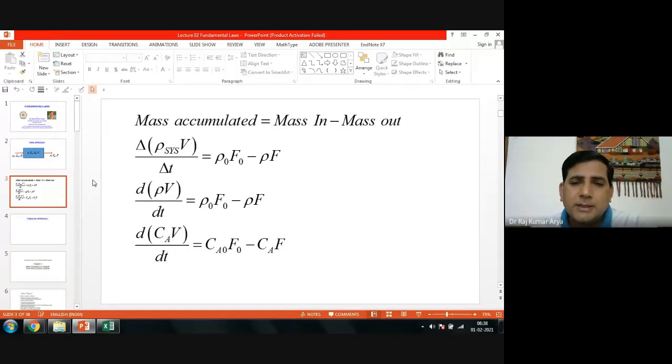So you might be wondering about the case of a reaction that may happen. For the reaction part, if you are putting a generation term here, even though that, mass will not change, because mass is a conserved quantity, right? So in that case you can write in terms of elements. If you are writing the same equation in terms of elements, you will not have the generation part. If you are writing for a component or compound, you may have some generation term here also, right?